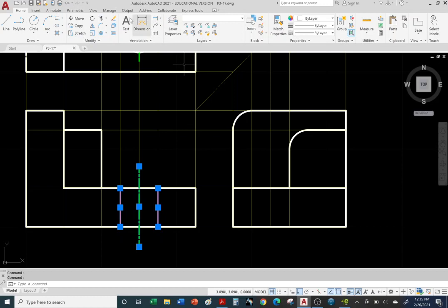All right, so let's go ahead and now let's use the copy command. Okay, so once again, copy command. So I pre-selected the 3 lines first, right? Then I hit copy. And I need to grab a handle, follow the instructions. Okay, so it's asking you, hey, grab it from a base point. So think of a handle. I'm going to grab it from here. So imagine a cup of coffee and you won't need to grab it from somewhere. Grab it from the handle. I'll pick this as my base point or handle point.